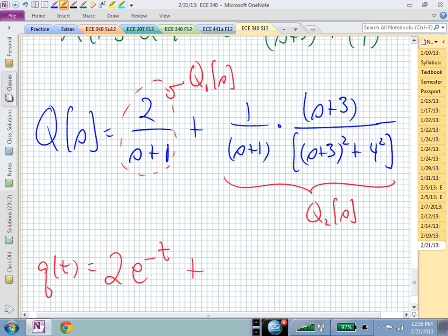Depending on how you want to do this, if you want to do the complex algebra, you might keep those as complex roots. If you want to keep everything real in terms of real coefficients, let's collect 2 denominators that look the same. One will be a cosine and one will be a sine that's exponentially damped at the same amount. And we have another term associated with this pole at minus 1.